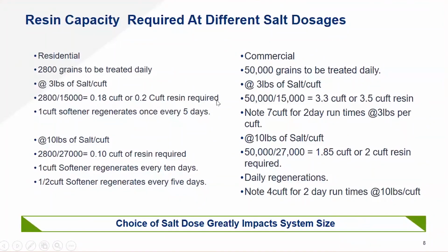I'm going to go with a cubic foot softener here. Why? Because I've got to buy my resin in a cubic foot bag. I'm going to select a cubic foot softener here. Well, that means that softener is going to regenerate once every 5 days in this scenario at 3 pounds of salt. I can deal with that.